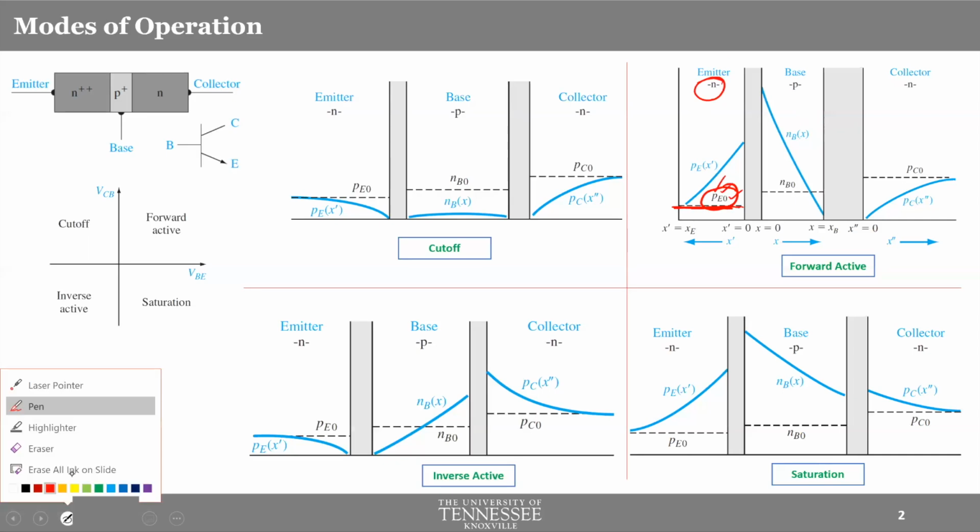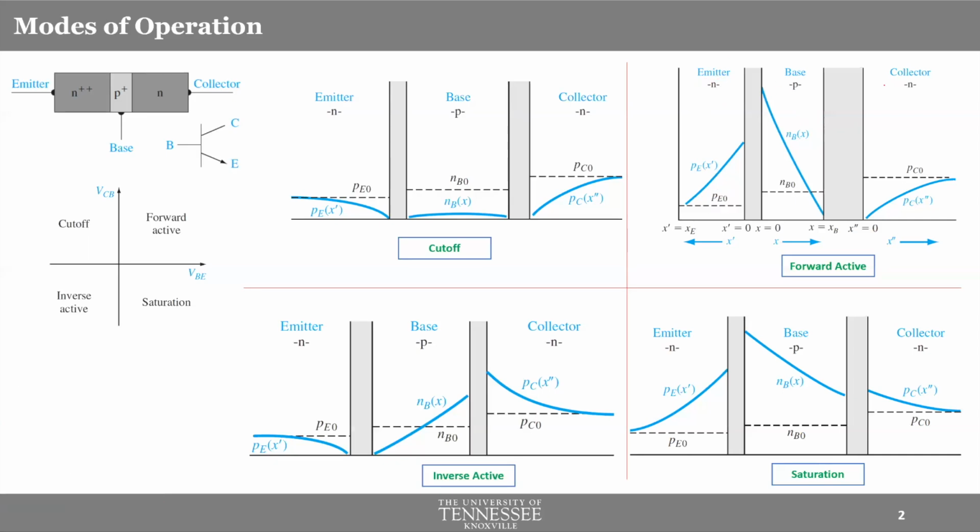How do you know? Remember, we are talking about forward bias and reverse bias, right? As soon as we start speaking in terms of biasing, that means your thermal equilibrium is no longer the case. So yes, these levels are there had we been operating in thermal equilibrium, but we are not. We are operating in a regular scenario, and that's what we will talk about. We will see what happens to this minority carrier concentration in a non-equilibrium scenario.